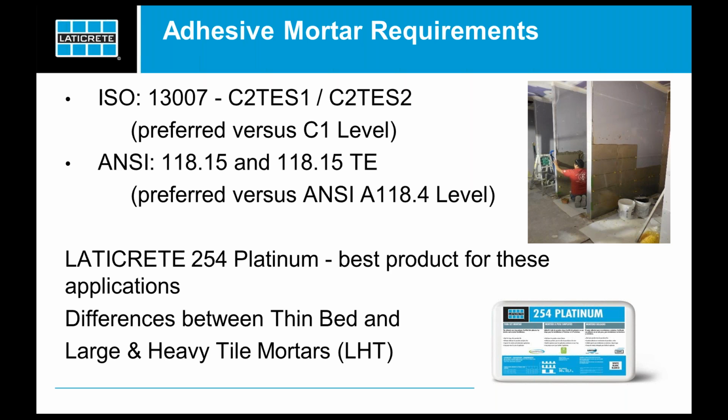It has high bond strength, high shear and high tensile strengths as well, and a long open time that allows you to spread the adhesive on both the substrate and the tile back while staying wet and tacky and getting great transfer and coverage. You'll also see that there are ISO standards. There's the C2 level. Those are the preferred levels versus the C1 level.